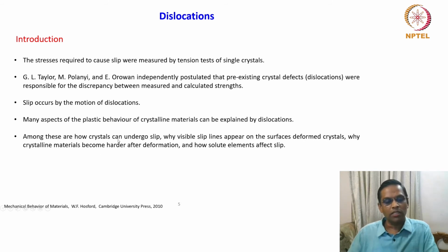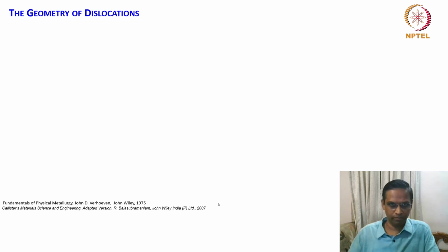Among these are how crystals can undergo slip, why visible slip lines appear on the surfaces of deformed crystals, why crystalline materials become harder after deformation, and how solute elements affect slip. So these are some of the questions they try to explain, looking at the dislocations behavior. That's why studying dislocation is important as long as you deal with crystalline materials deformation behavior.